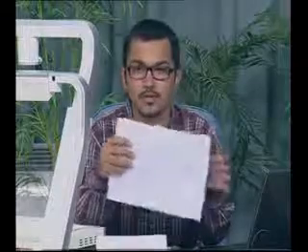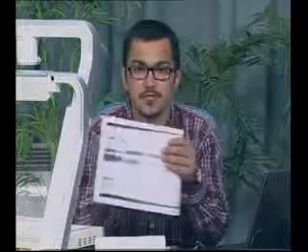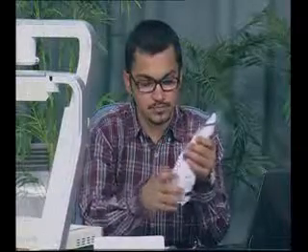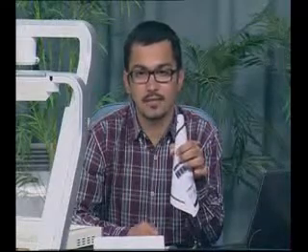For those of you who have not understood the development of surfaces, what is basically development of surface? That is the question here. Say this is a cone that I have. If I say you should develop the surface, then I'll just unwrap the cone, so I will have the surface with which the cone was made.